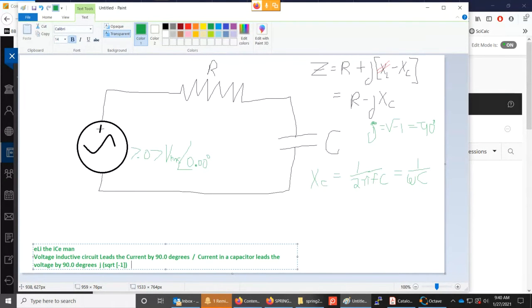Well, in engineering, it's not an imaginary number. I mean, we still call it an imaginary number, but what it really means is there's a phase shift, okay? So there's a 90-degree phase shift. That's what the mathematical value of square root of -1 in electrical circuits means: there's a 90-degree phase shift.